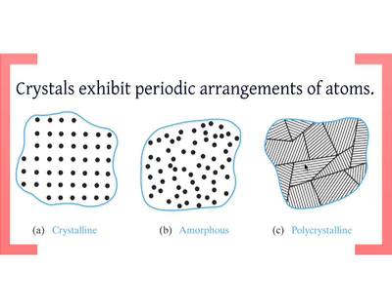the atoms are arranged in a periodic fashion, but outside that region, the periodicity could be different, the orientation could be different. So you basically take a whole bunch of little crystals and put them together, that's polycrystalline. Okay? And all of these are important in semiconductor electronics. Of course, crystalline silicon is probably the most important one, but all of these are equally important, as we will see in the rest of the class.